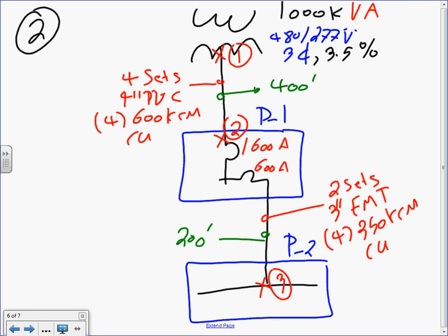When we do short circuit calculation, guys, we do line to line. Line to line, for the most part, is the worst scenario. When you grab phase A, phase B, phase C, you bolt them together and you flip the switch. That's the worst scenario that you're going to encounter. Line to ground and line to line, 2 lines together, almost always will be lower than the 3-phase. Sometimes it's not true, especially for the ground fault. But for the most part, if you size based on the worst scenario, which is the 3-phase short circuit, you are covered for 90% of the situations.